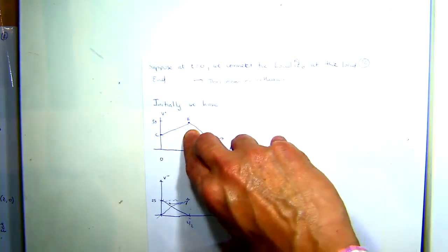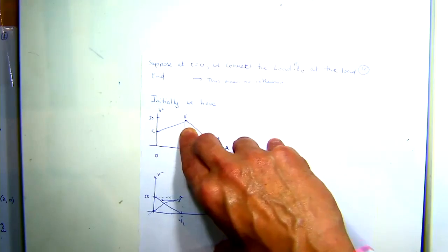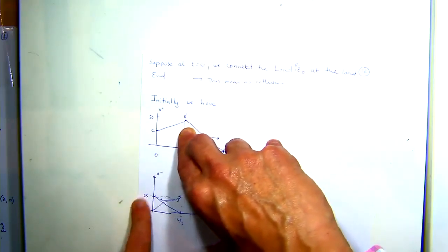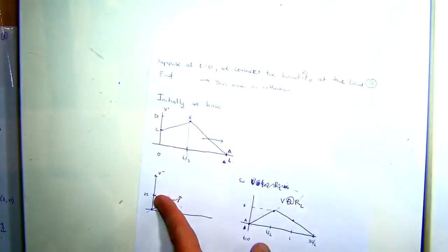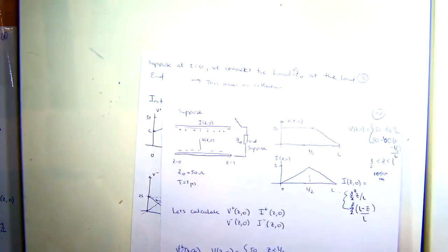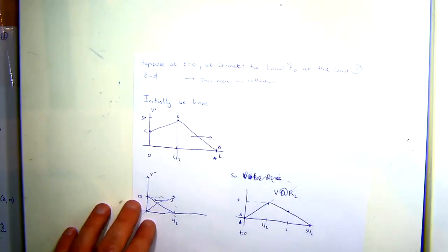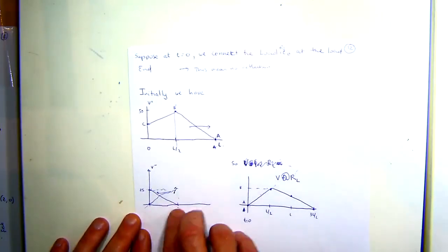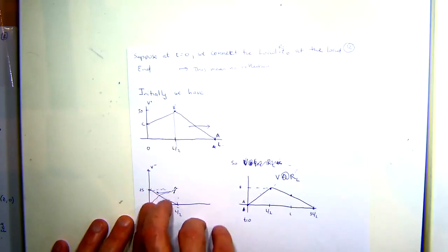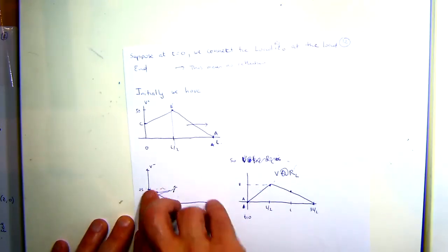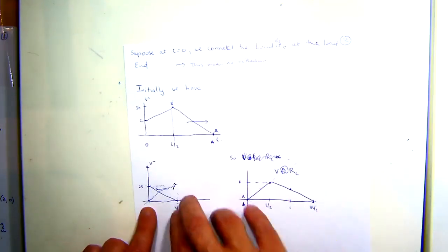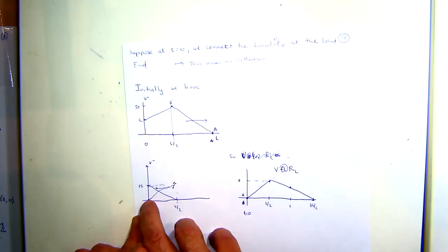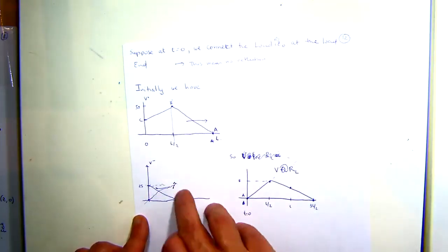Now, likewise, we've got the negative going wave, right? And all I said is, because we've got the negative going wave, it's also going to hit the discontinuity in this transmission line, because remember it was an open circuit. And we know for an open circuit, gamma is a positive one. And essentially as this hits, this component is now going to start moving in the opposite direction. So this is going to be essentially mirrored about this point.